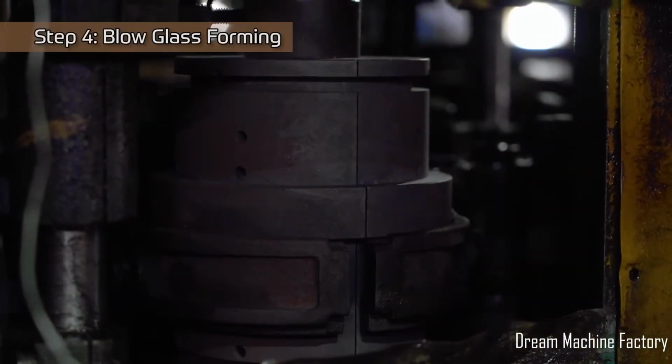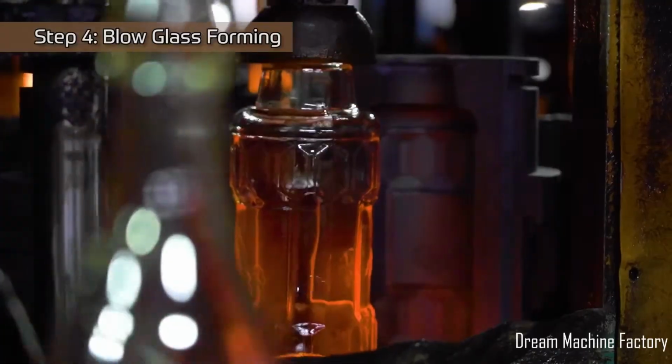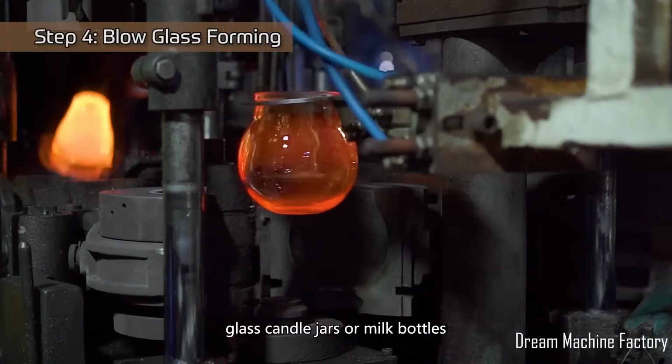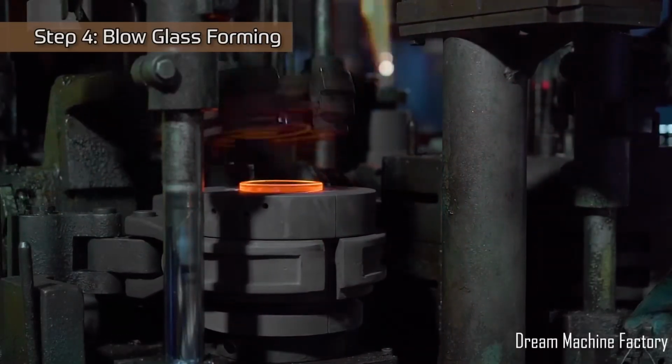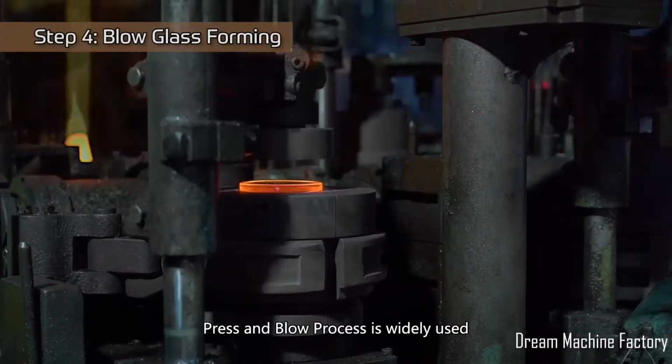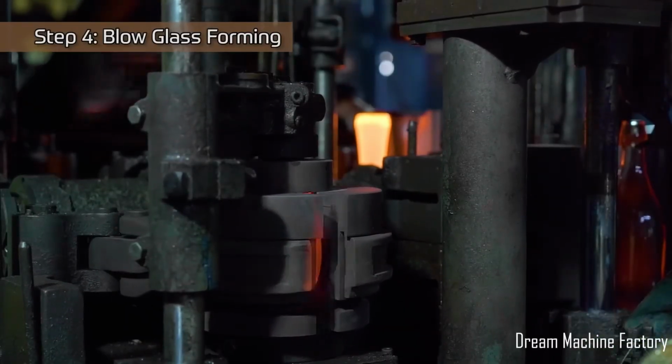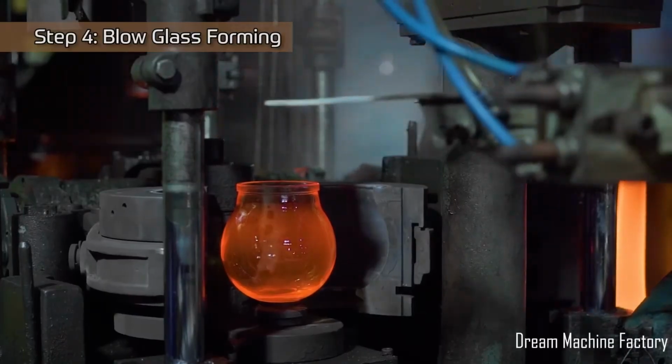For wide-mouth containers such as vases, jars, or milk bottles, the press and blow process is preferred. A plunger presses the gob into a parison mold, which is then transferred, reheated, and air-blown to its final shape. Both methods ensure precise dimensions and consistent quality.